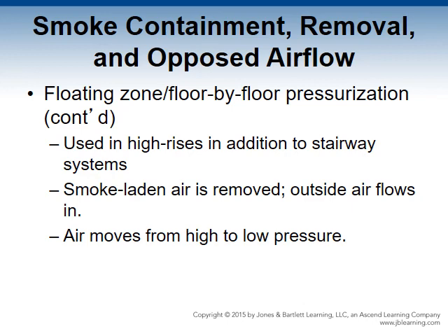pressurization. In addition to removing smoke-laden air, outside air flows to all other floors. Outside air also moves from the pressurized floor to exhausted floors through gaps and cracks. Because air moves from high pressure to low pressure areas through the path of least resistance, some of these systems provide pressurization in stairways and elevators.